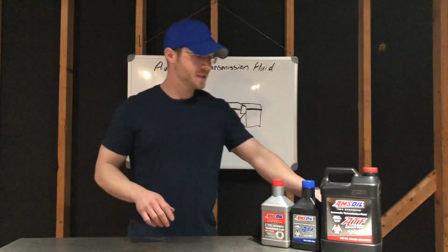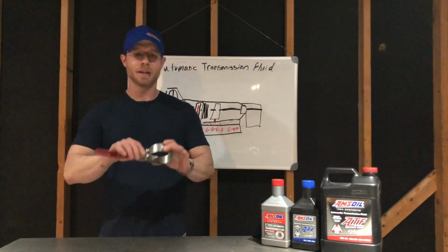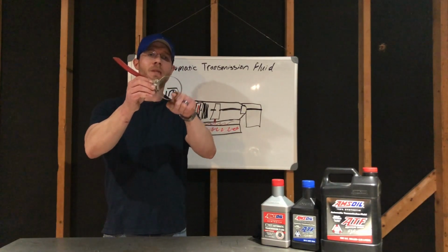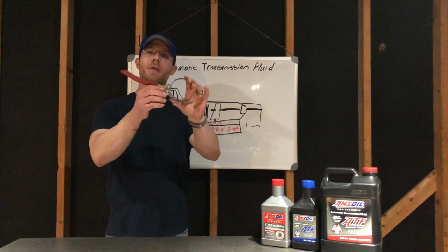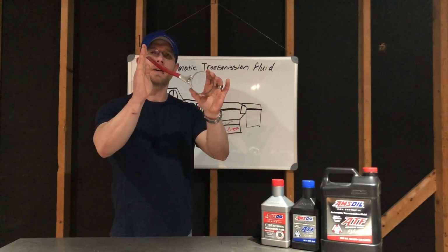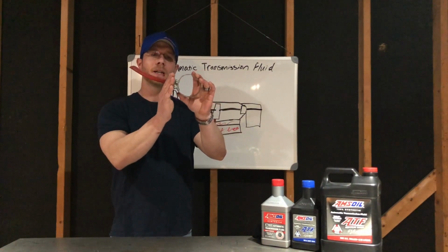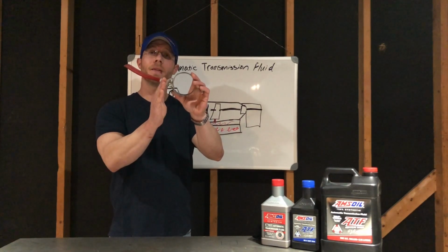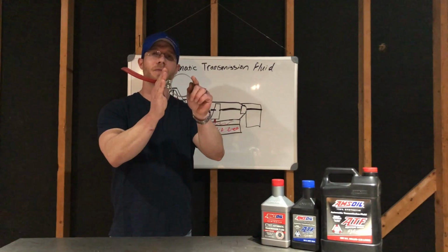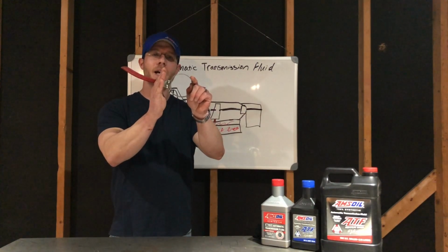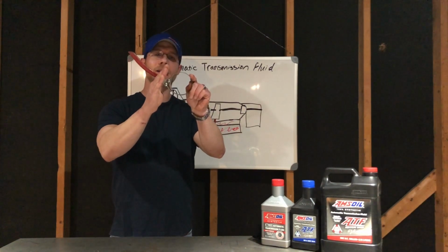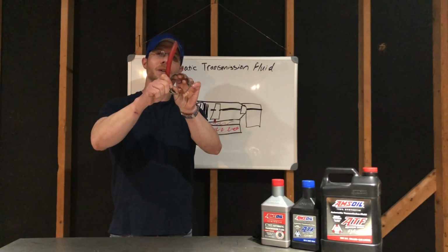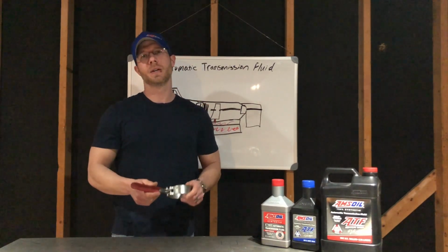One of the other types is a band. So you've got a gear set in here that spins freely, and then when you want to engage it, the solenoid applies fluid, it opens up, and then the valve applies fluid to the piston, and then the piston raises and it closes the band, which then locks in the gear set and allows it to turn.